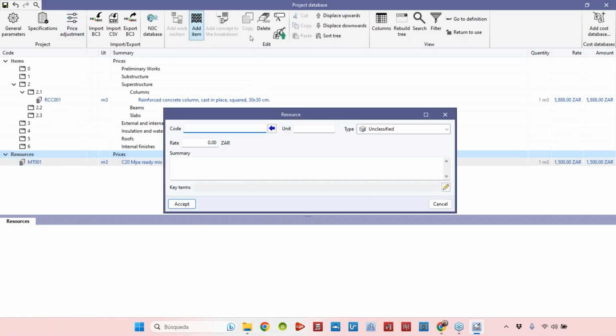That's going to be, for example, the steel reinforcement bars. Let's add here just one type of steel, like B500, for example. It's enough. Just some details are here to have. Of course, you can add more details if you want. This is going to be the material number 2, for example. And the unit in this case is going to be kilograms. Okay, it's going to be also materials, and the price of each kilogram would be like 32. Okay.